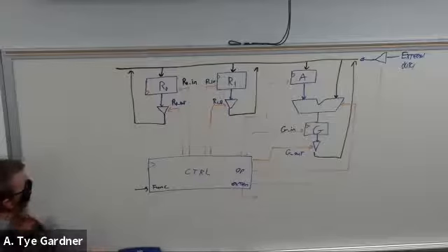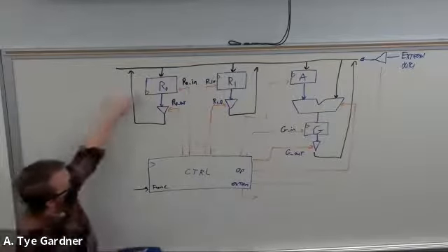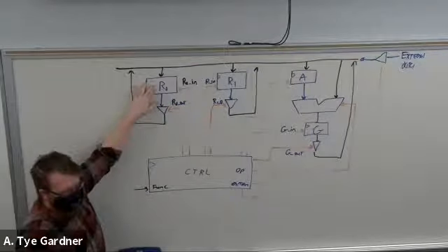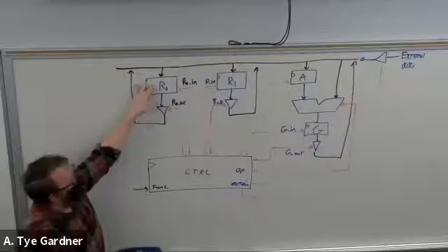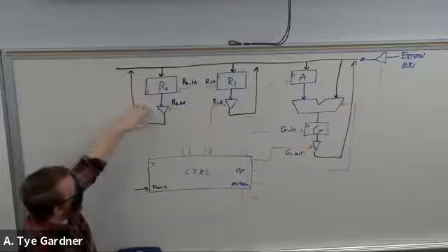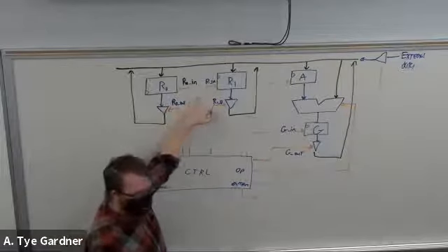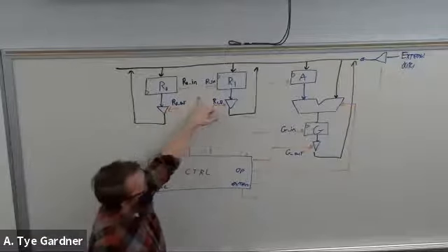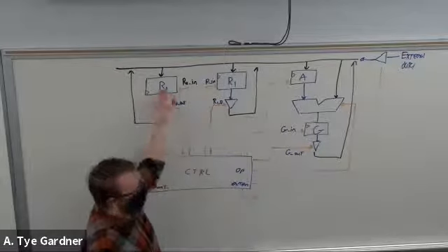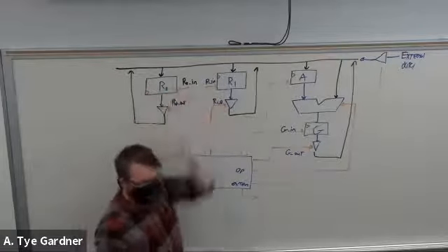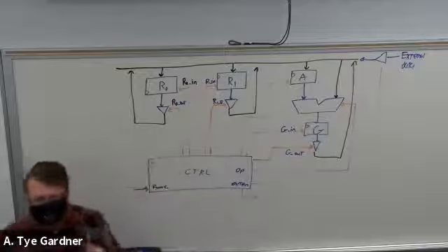So at the first clock edge, 3 gets clocked into R0. At the next clock edge, you want to have dropped R0 in, assert R1 in, and bring a 7 in. So now I've stored a 3 and a 7. That takes me 2 clock cycles, right?